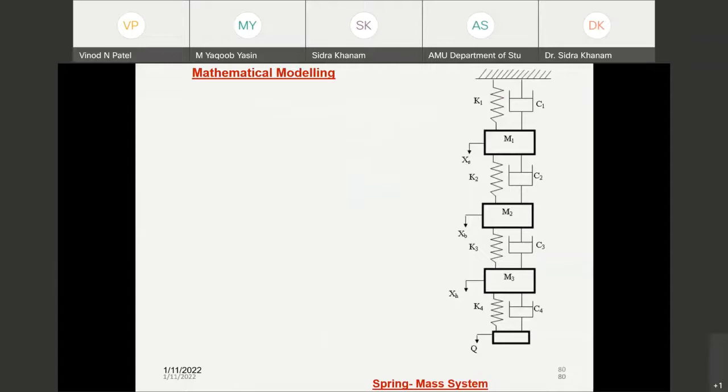Now, this model was again refined by considering some additional damping effects which were neglected in the last model. The damping due to the lubricant was not considered in the last model. So the additional C2, C3 will provide additional damping available between inner race and ball, and between ball and outer race.